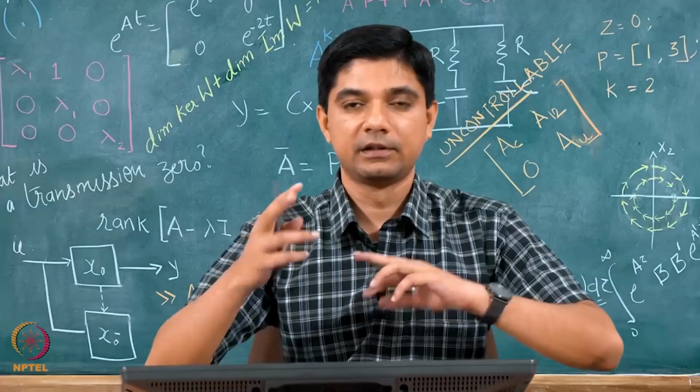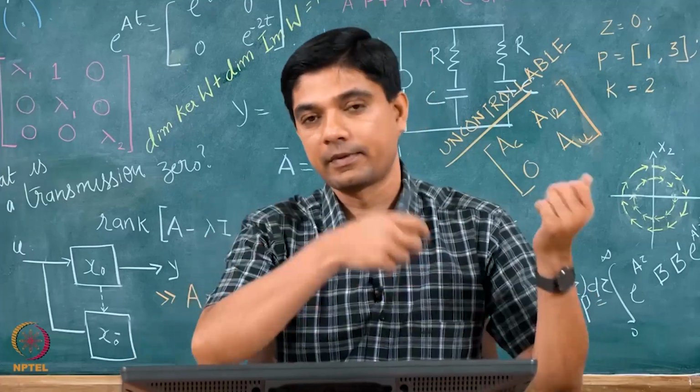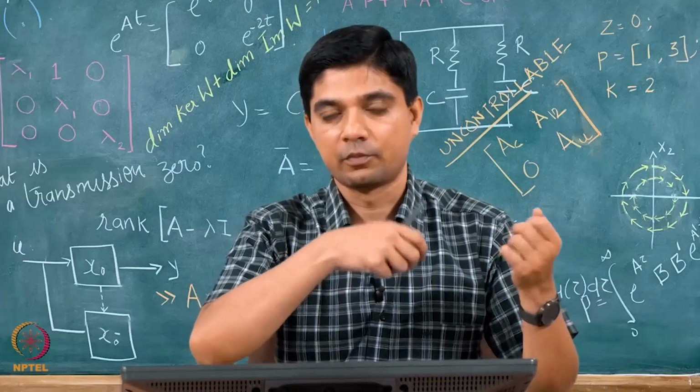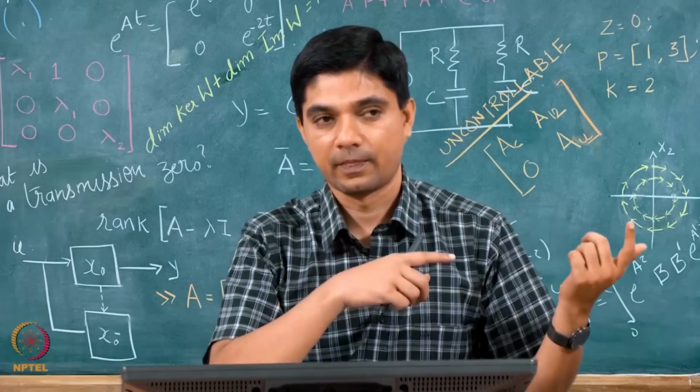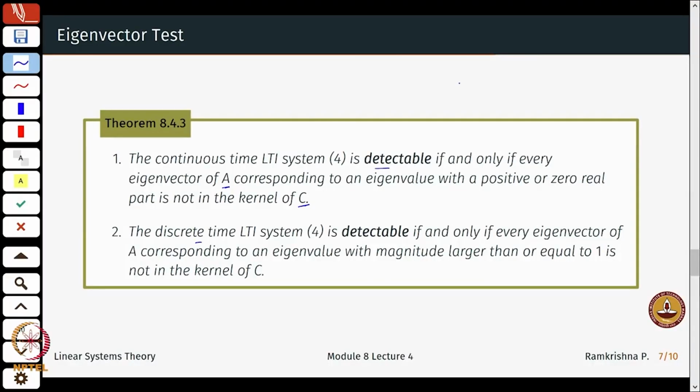Similarly, for the detectable case of discrete time systems, you can do these proofs from scratch, or you can also write down the dual system and just compare with the controllable properties of the controllable decomposition. So, here if the rank of O is Q in the dual system, the rank of C, the controllable matrix of the dual system, which I think we denoted by A bar, will be Q, right. So, here the unobservable modes will show up as the uncontrollable modes, okay, and so on, right.